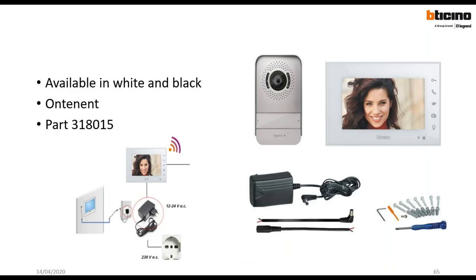Very competitive. Cabling is done with a simple power supply, like the charger of a telephone, with this cable that gives the possibility to put the power supply in a distribution box or somewhere else. So if you don't have space in the box behind, you will arrive with 2 + 2 wires, 2 connected directly with the internal unit, and 2 that come from the power supply.